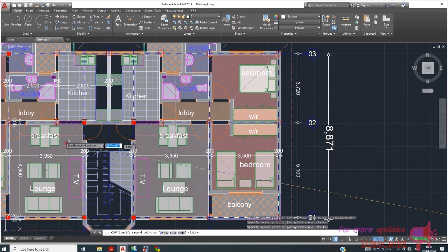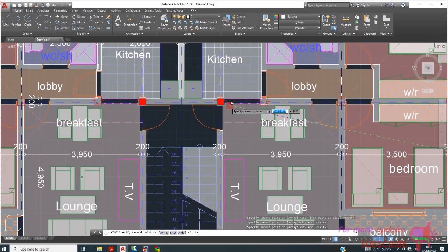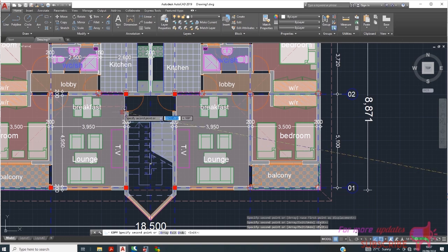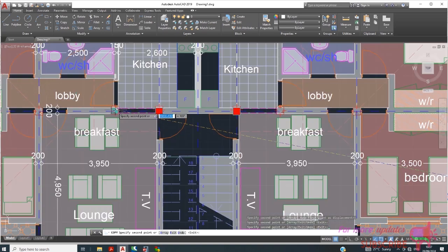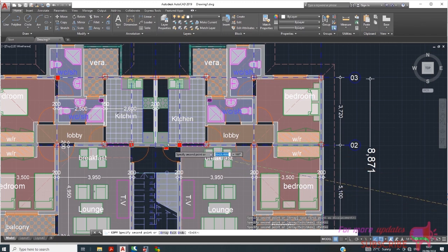And even without that water tank, staircase is very critical. So it's important that you try to make sure that you have columns for both landing one and landing two to support that staircase.